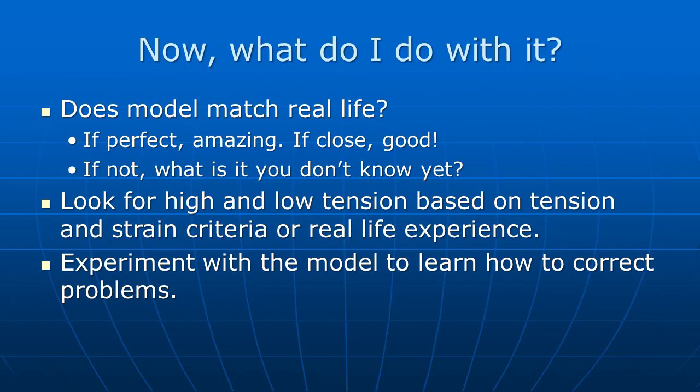And you can do experiments. Now, this is where you might say, okay, this is running my normal raw material, but I want to run something lower modulus. Is it going to run? What are my tensions going to be? Are there speeds of rollers that I might adjust? And do it in the model before you get out on a converting line and have to try and make it run when you're using raw materials and consuming production time. And so you can do your experiments on the model, you can do your what-if questions, you can do your troubleshooting, you can do equipment modeling changes, and experiment with it. Learn what happens if I change this roller.